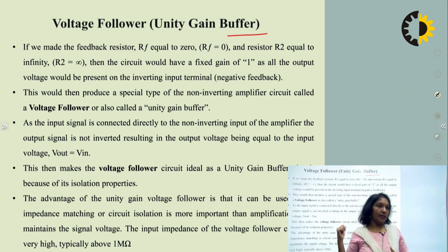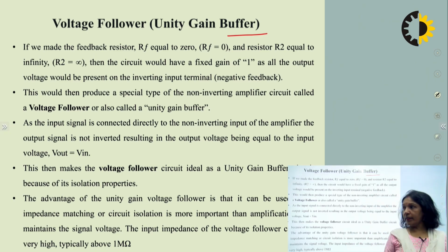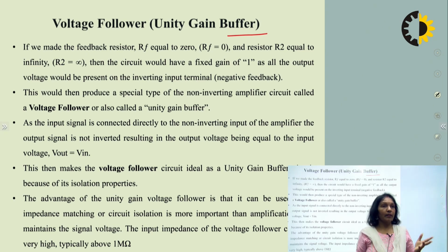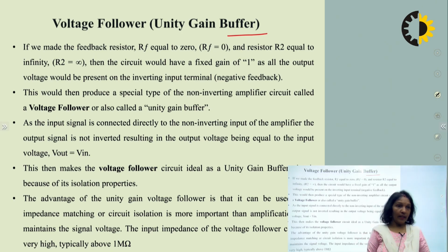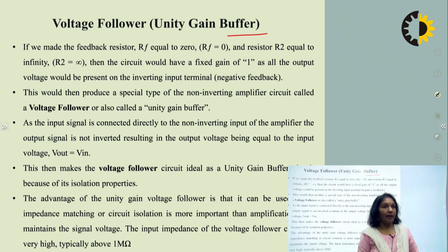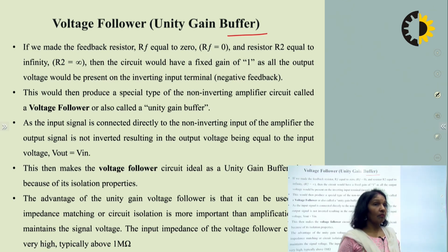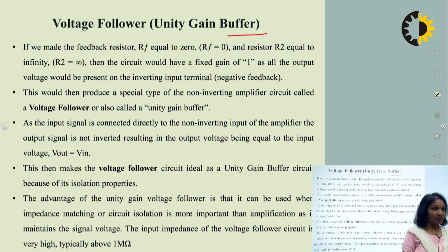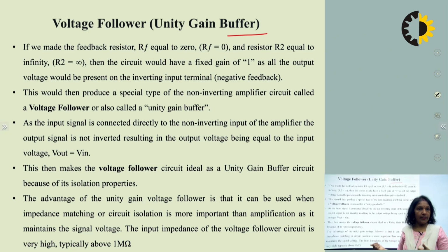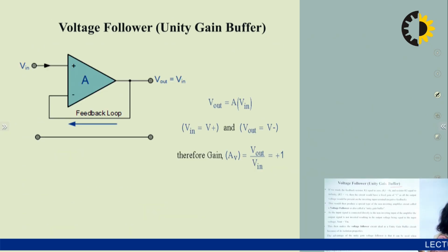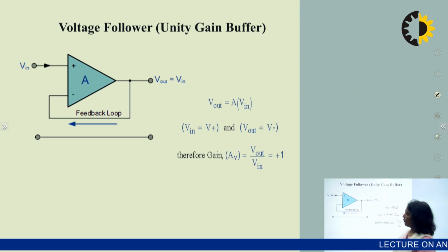The same type of circuit can be created with the help of the op-amp also. The transistor amplifier will do the same work, and the operational amplifier is the same type of amplifier. The only thing is that a single op-amp can serve the purpose in the case of the unity gain amplifier. So this is the circuit diagram of the unity gain amplifier.